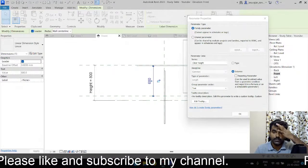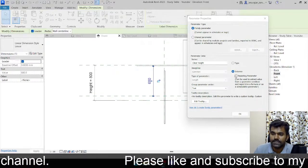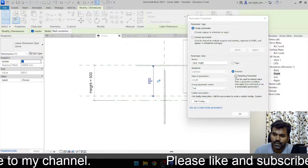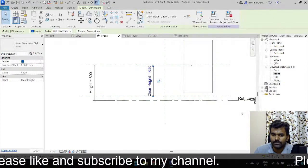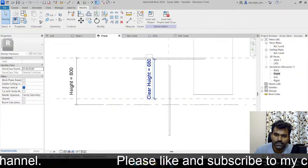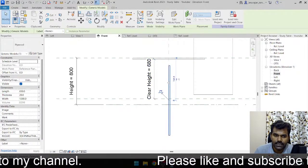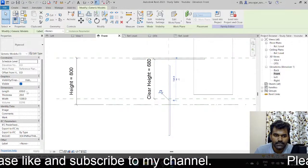Okay, so just keep this as instance, and you can see here a reporting parameter can be used to extract a value from a geometric condition and report it in a formula or as a schedulable parameter. So now we can see there is a clearance, the clear height here. Now I know the clear height, and I'm going to match this height to this plywood. Let's just match the height here.